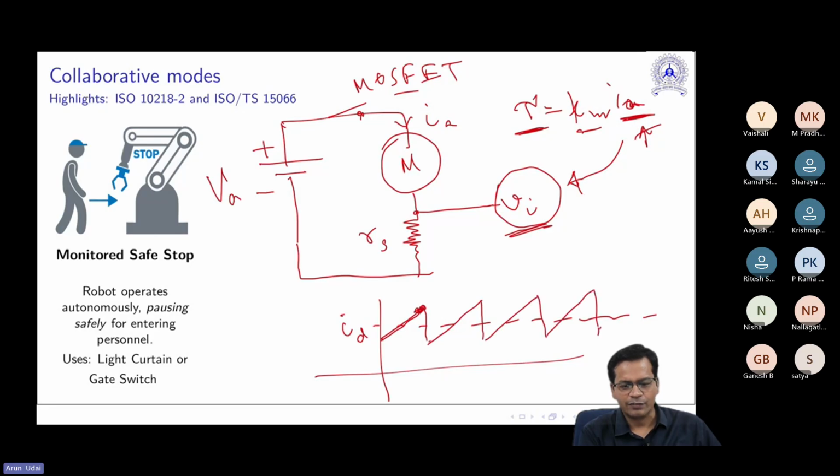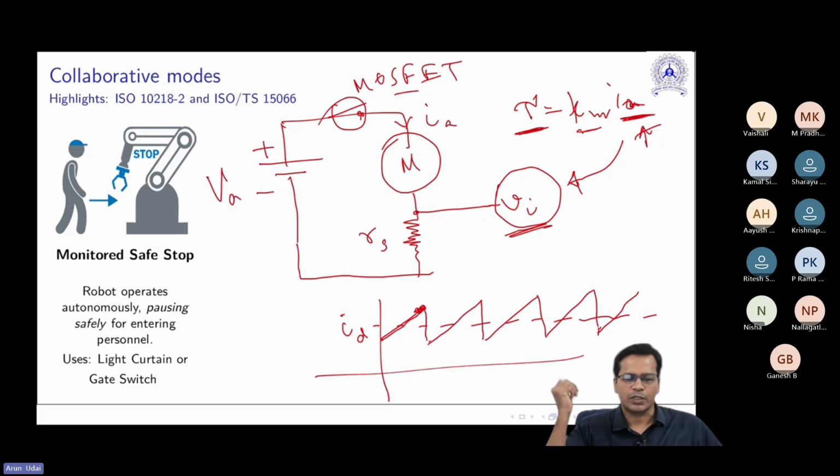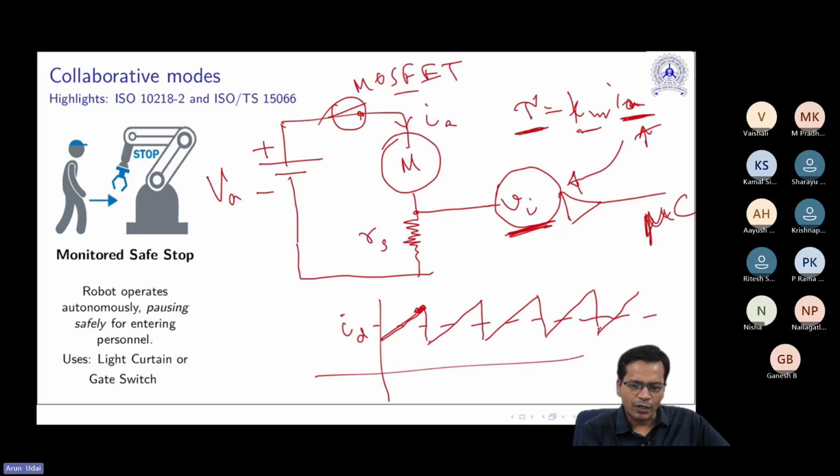Such an easy language. Today I have taught you what is a chopper drive, how that is done. You have a MOSFET switch here, which can switch on and off this motor. So you are sensing the voltage across a small value resistance, feeding it back to your microcontroller. Microcontroller can read analog input. If this voltage is very small, maybe you can put a small gain here and put it to microcontroller analog input channel. You read this. So you can switch on and off this motor.